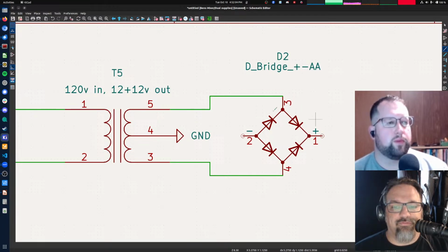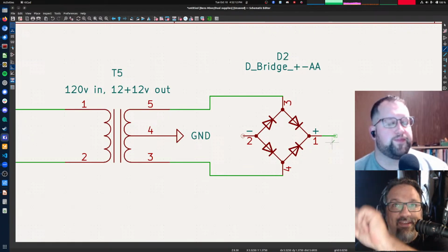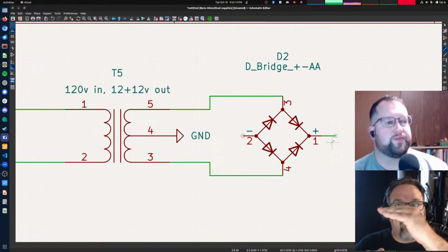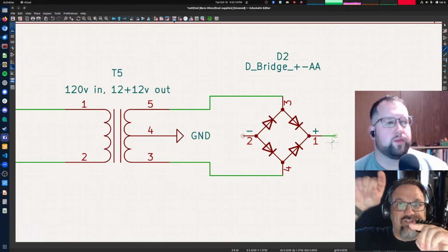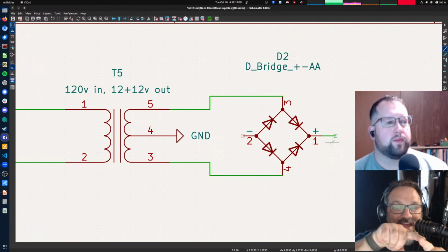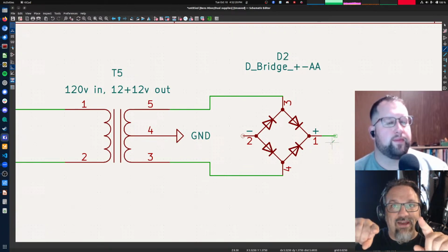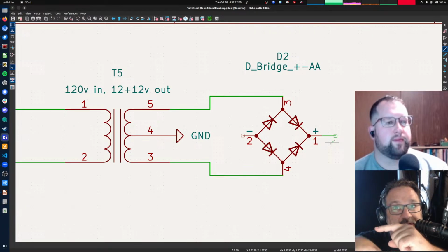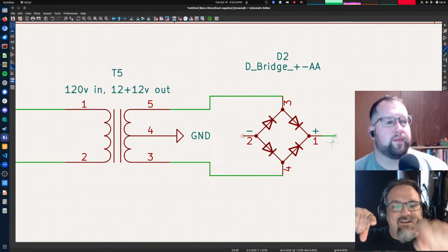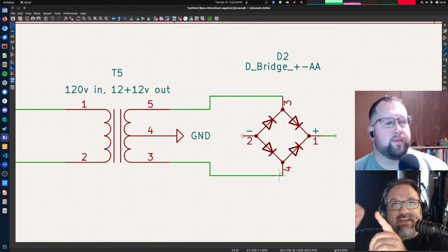So through diode magic, this will be a positive voltage. It'll be a positive voltage going up and down, but it never goes below ground. So it's still got these giant humps in it, like half of a sine wave, and it goes back down to 0. It doesn't go below 0, but then the other side is now generating the other half of the sine wave.